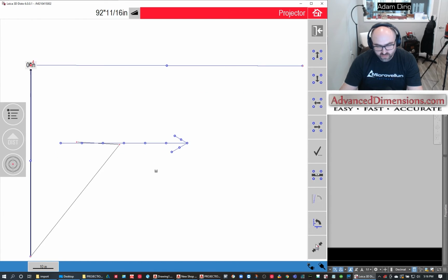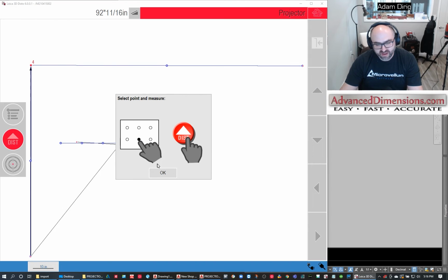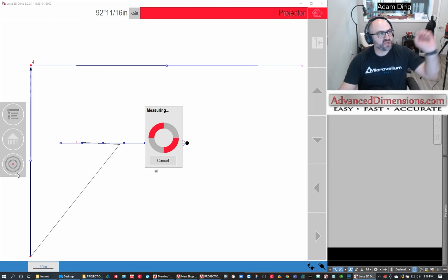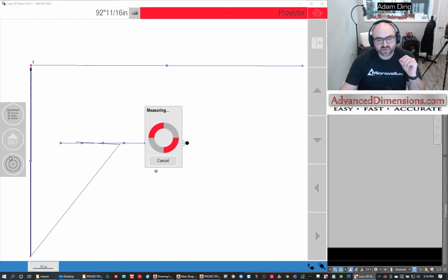So I can just say, hey, I want to align this one to this one. And go, whoop. Now, if I wanted to, I could test and be like, hey, if that was the starting point and I knew it, if one of these was a definitive starting point, I would say, okay, let's test it. But if this looks good, I'm just going to hit check. And now I'm going to start projecting those points. And it's going to project it right where it's supposed to be on the wall. So it's extremely precise once you get it set up.